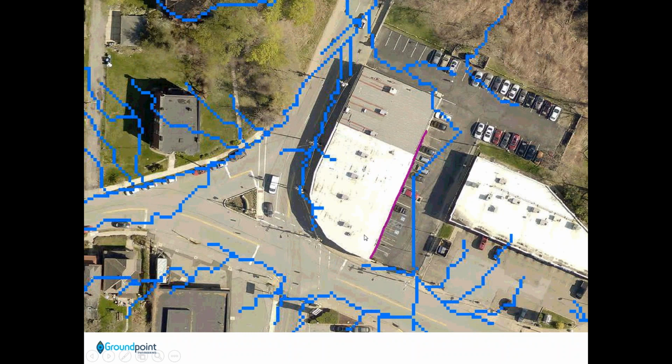So sometimes people ask me, well, how come you didn't just connect the flow in the gutter here and have it route around the building on the front? Because you can clearly see the gutter and the curb along the edge of the road. And the answer to that is in the data. As you zoom in, now we're looking at the LiDAR points, you can zoom in and look at the elevation values of the individual points, and you'll see that it's actually uphill. So the points between here are actually higher.